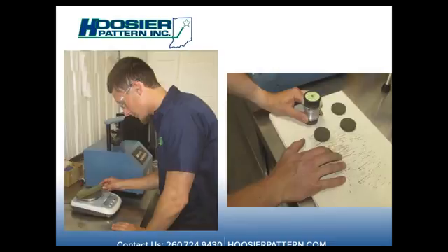We'll be happy to share these test results with you or send you coupons for you to verify in your sand lab. And here are some pictures of our sand lab and our operator checking them. The one on the right is a scratch test, a non-destructive test. Foundries use it now. It's just a telltale sign if your cores are weak or overly strong. It just gives you an idea. On the left, we're weighing the bars. We always weigh them to make sure they're the right weight range and not too dense.